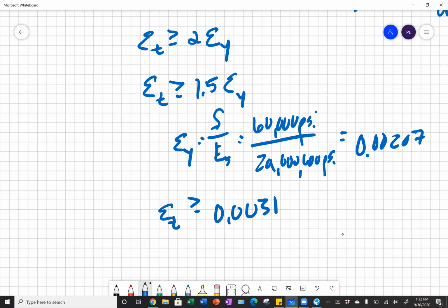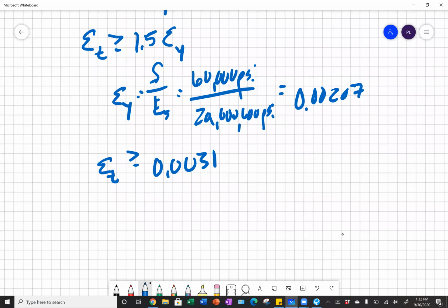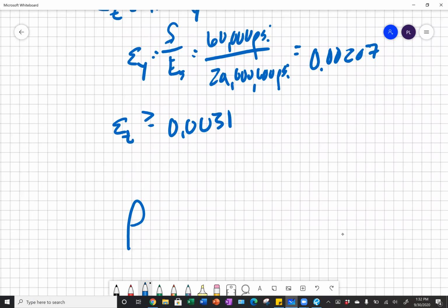And that rho max equation, if we wanted to convert it to a reinforcement ratio, and we look in the TMS 402 document, rho max, our maximum reinforcement ratio, is our maximum area of steel reinforcement divided by b, our width, times d, our effective depth.